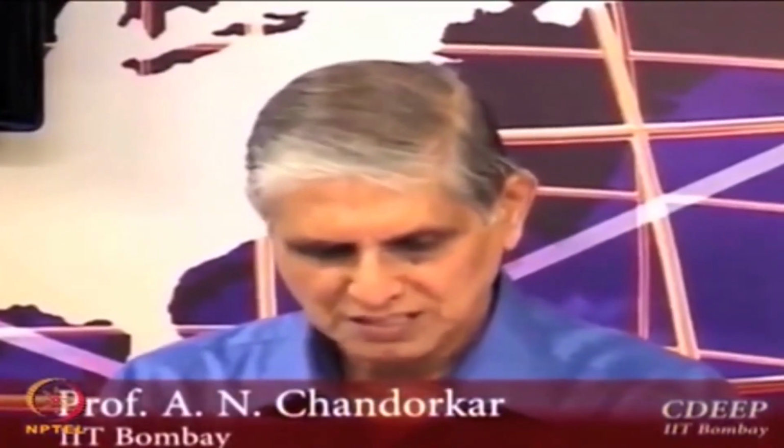We were talking about the current and voltage references. We were looking for some kind of current mirrors, and we looked into the Wilson current mirror, and then we said okay, it has a good output resistance, it has a feedback, so it stabilizes faster and better. All that we did last time was the Wilson current mirror. So let us start with the part ahead.